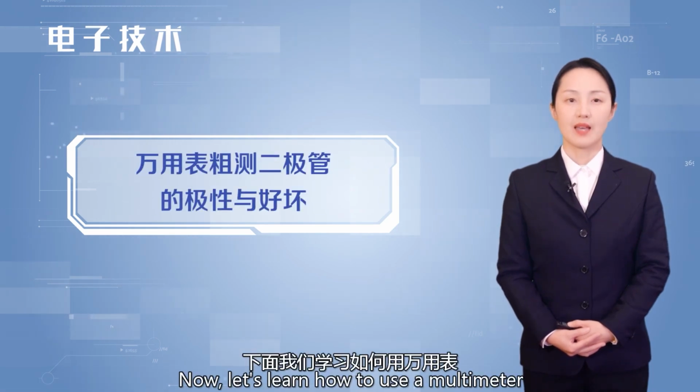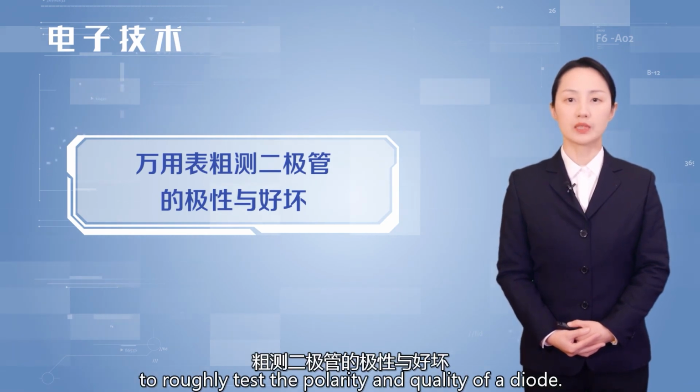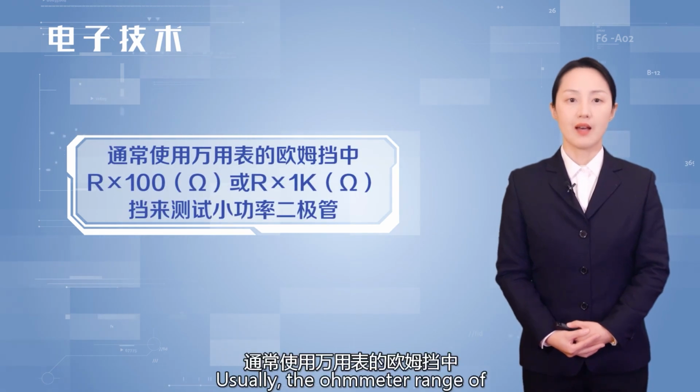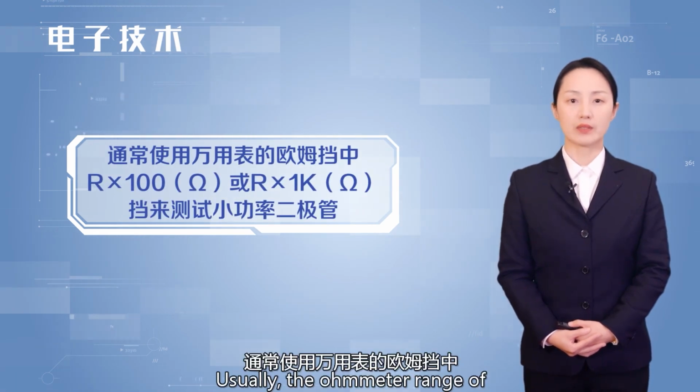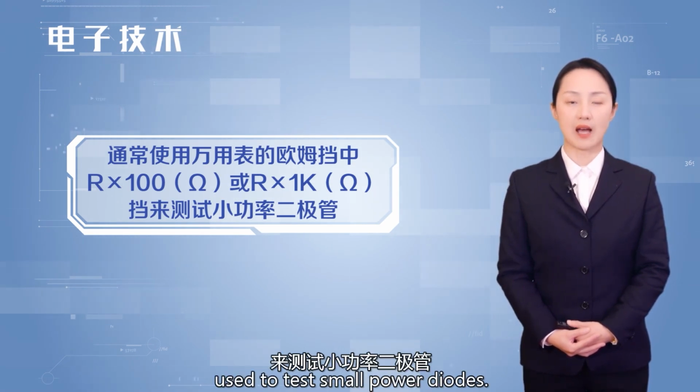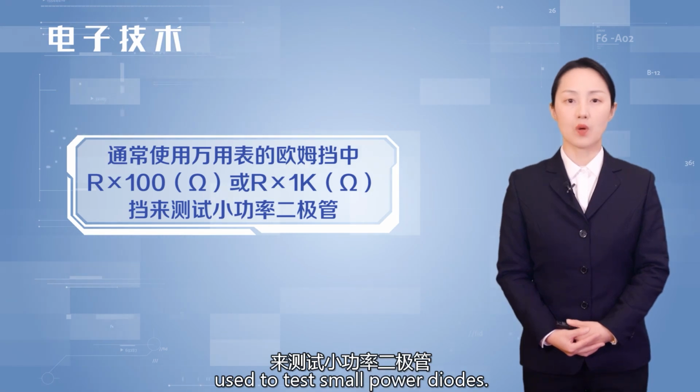Now, let's learn how to use a multimeter to roughly test the polarity and quality of a diode. Usually, the ohm meter range of R times 100 or R times 1K is used to test small power diodes.